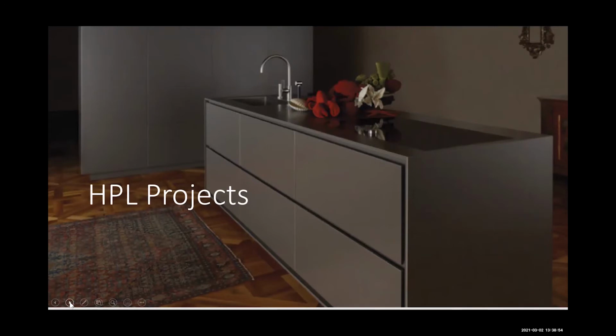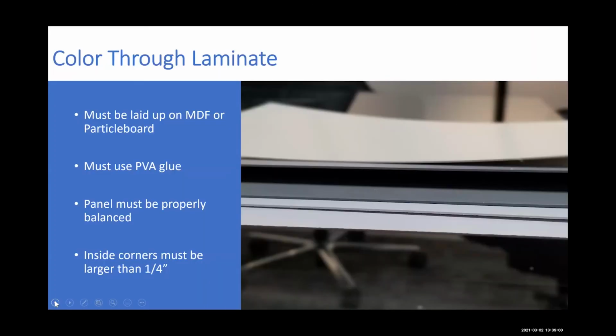There's also a couple of other things. When you do full color through, you cannot use plywood as a substrate, and you have to use PVA glue. And it has to be balanced equally. Typically, full through colors are a little bit thicker than regular laminate. So therefore, your backer panel has to be the same thickness, or you will get cupping.